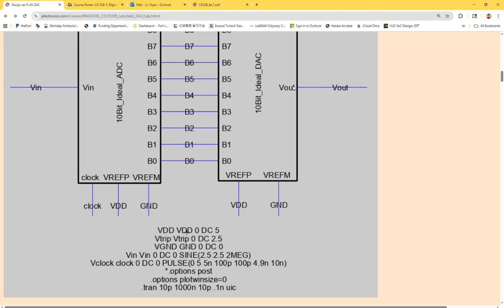That's 2 megahertz. So in LTSpice, if you want to make megahertz, mega ohms, or mega something, you have to type MEG for mega. If you directly put an M, even if it's an uppercase M, it's considered as milli, not mega. Keep in mind. And you create a clock.